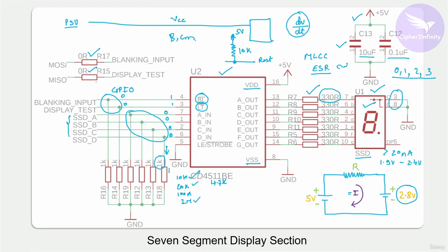If you observe, I have actually used the same pins that we used for programming the microcontroller. When I was designing the circuit, I was not sure whether I should use these pins or whether I should connect these pins directly to the ground. So that's the reason I have included the 0 ohm resistor.